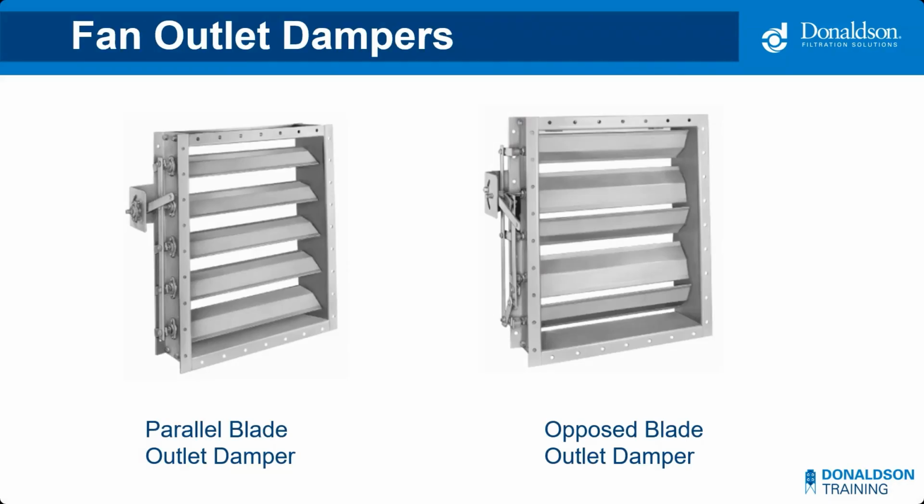Since clean filters have much lower static pressure, the airflow will be too high if we leave the damper fully open. Throughout the life of the filters, the operator should adjust the damper as needed until it's fully open to maintain the design airflow. Fan dampers can either be on the inlet or the outlet. Here's a couple examples of outlet dampers.